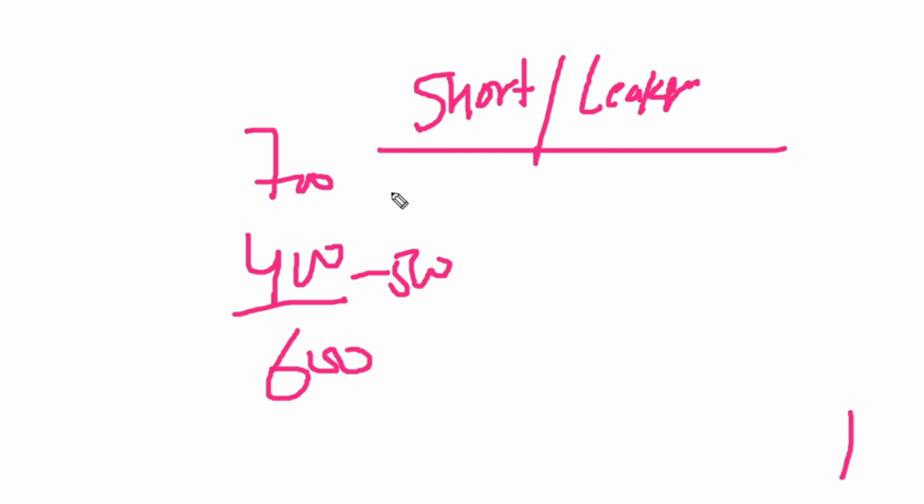From the connector side. First I'm talking about the connector, not the circuit. Step by step we talk about this line. I'm discussing at a deep level, so you can check each and every step. I'm giving you each and every detail. If you get it both ways, reverse side also and forward side, that means this line has a short. So what to do? On this line, the anode line, you get a 0 ohm resistance, right? First you remove this resistance.